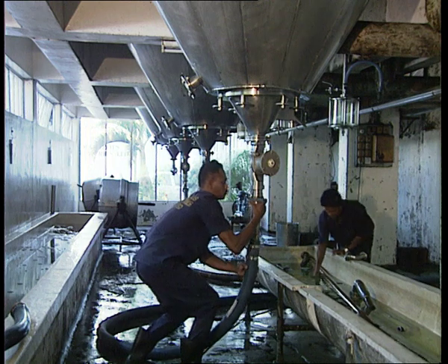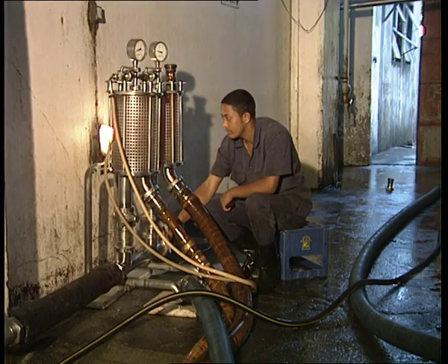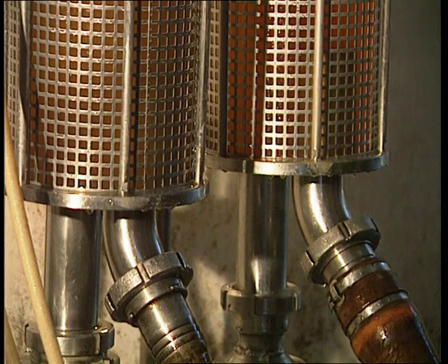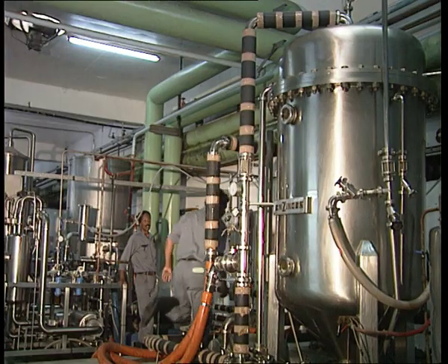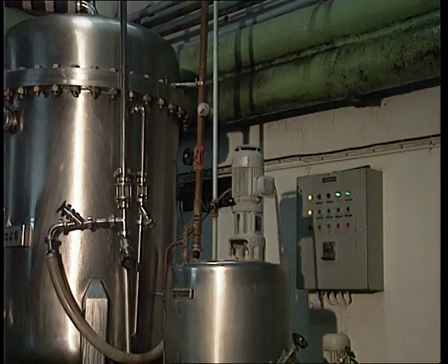From the maturation vessels, the final filtration of beer is done with the use of a candle filter. The polishing of the beer is necessary to give the beer the required color. Beer is being filtered and carbonated prior to packaging. The filtration process is the final process whereby the beer is being polished to give it the bright golden color.